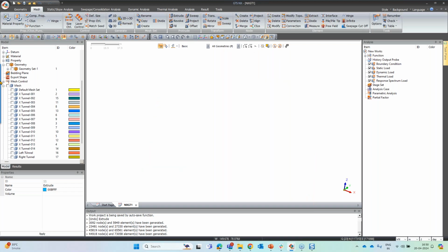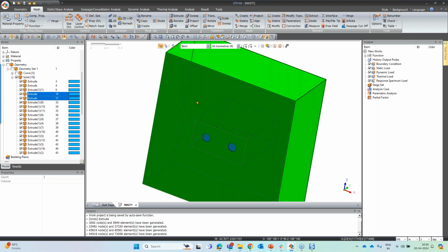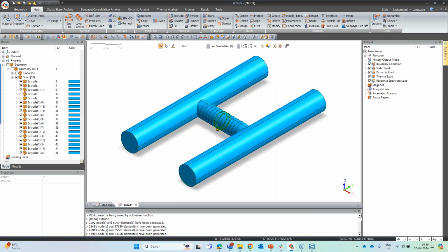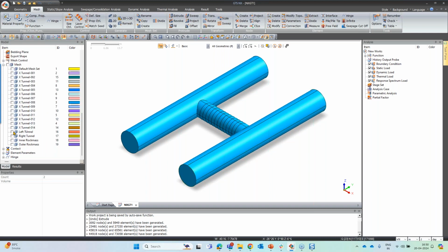Let's hide the meshes. And then I'm going to extract a 2D mesh out of the 3D meshes. So this entire solids have already been created with the 3D meshes, right? So using the extract option in this software, we will extract the 2D meshes out of the 3D meshes. So that's what we will be doing. So further, at first, let me start with the cross tunnel lining.